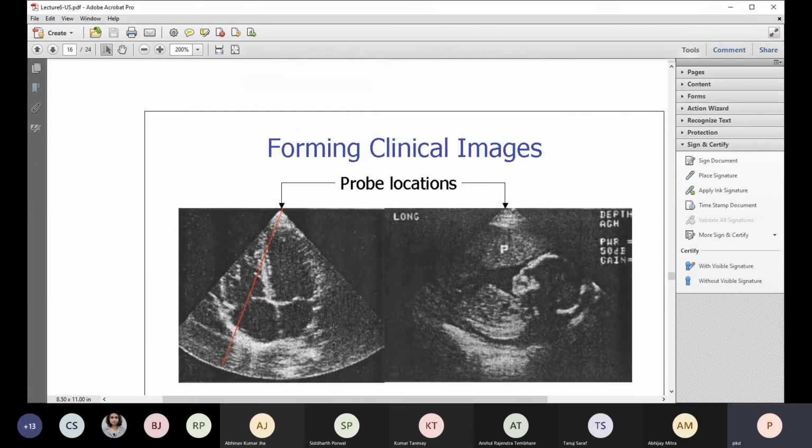So this has been shown here. Corresponding to various lines, along each line the reconstruction will be made. The pixel values will be set in a rho theta coordinate, and then we can convert to the rectangular coordinate wherever necessary. That's why ultrasound images are displayed in a conical form, because the basic coding is done in the rho theta coordinate.